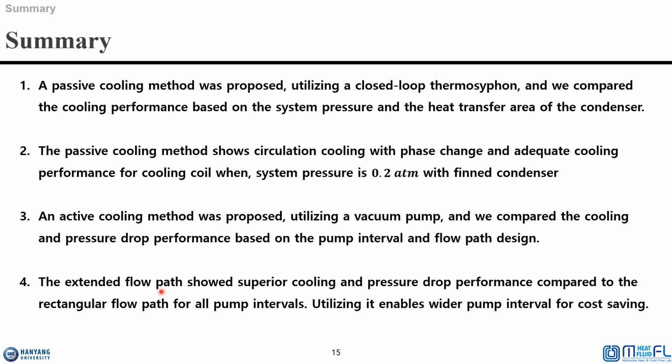In summary of the entire presentation, first, we proposed a passive cooling method utilizing a closed-loop thermosiphon and compared the cooling performance based on the system pressure and the heat transfer area of the condenser. And second, the passive cooling method enables circulation cooling with phase change and achieves adequate cooling performance to cool the coil below the temperature limit when the system pressure is 0.2 atm with a pinned condenser.